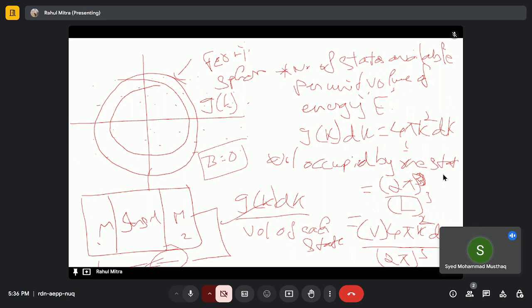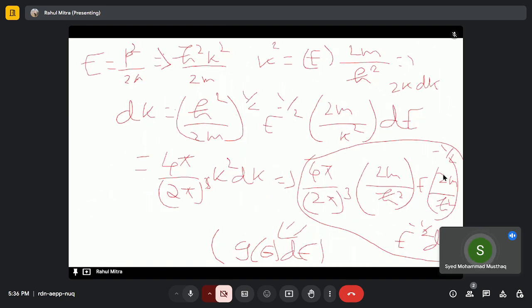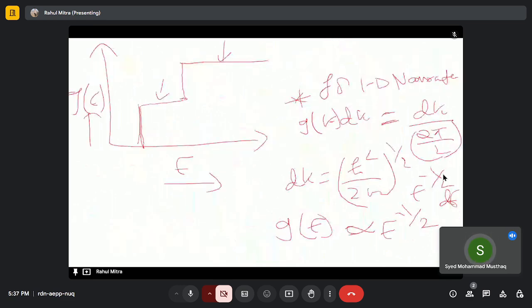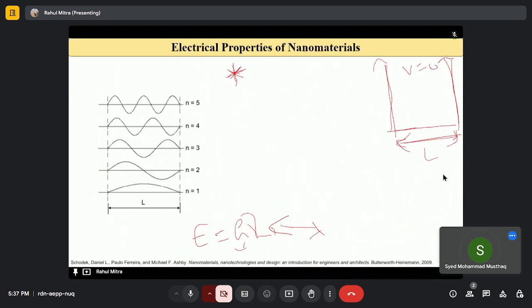These can also be used for the dielectric behavior. A large number of grain boundaries in nanocrystalline materials is expected to increase the dielectric constant. For example, nanocrystalline TiO2 has a higher dielectric constant compared with coarse grained samples. This is due to the following reason: under an applied electric field, the positive and negative charges are segregated at the interface and will lead to some form of polarization. So these are the different applications for 0 to 3-dimensional nanomaterials in different cases.